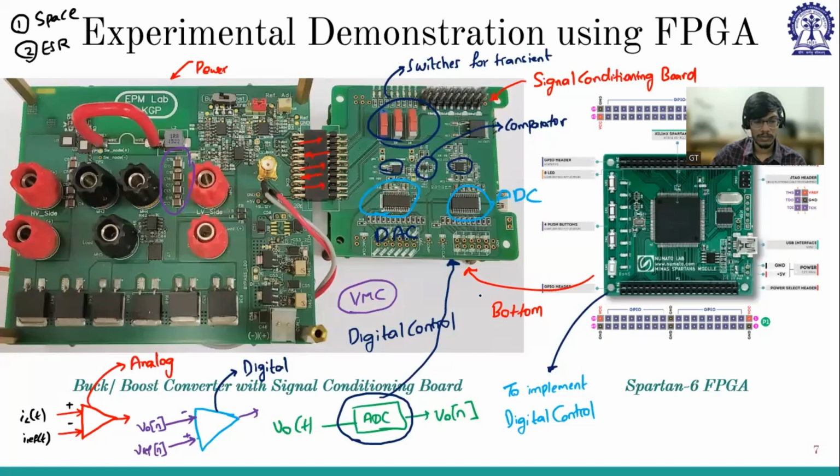Okay. So that's why we always choose SMD, which has lesser parasitics compared to through hole. But if your application demands through hole, then you have to go through hole, and you should consider that additional parasitic also.